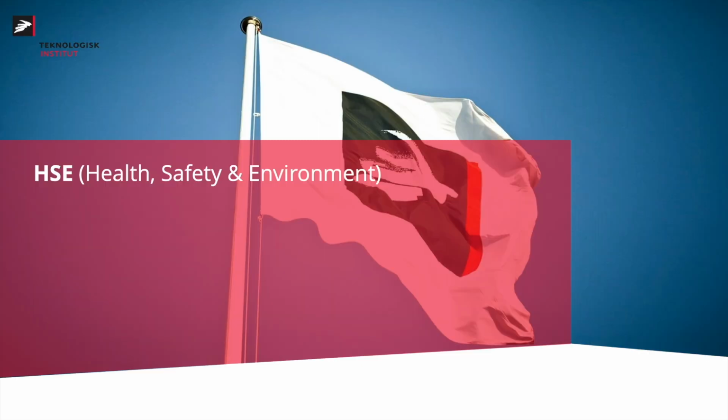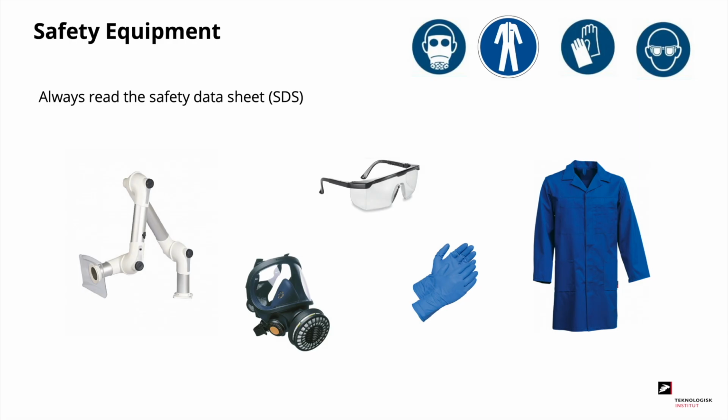Let's start with health, safety and environment. Before printing with VPP, you should always read the safety datasheet. Furthermore, you have to use the proper safety equipment. This includes ventilation, masks, glasses, gloves and proper work clothes.